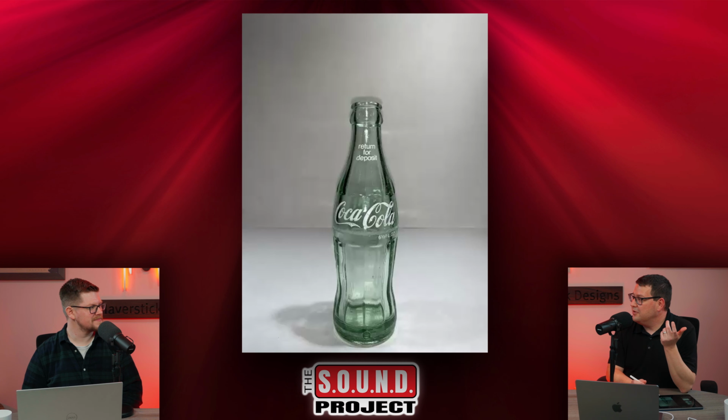Sure. The next thing we're going to talk about is Helmholtz Resonators. Mm-hmm. And Helmholtz Resonators are basically these tuned devices that, again, can help absorb sound. We're all familiar with Helmholtz Resonators, whether we know it or not, because one of the best examples, I'll show it on the screen here, is a Coke bottle. We've all kind of blown across the top of a Coke bottle, and you can make a tone. Mm-hmm. Well, that Coke bottle is tuned for that frequency, and that can help absorb that energy if you put a bunch of Coke bottles in your room.